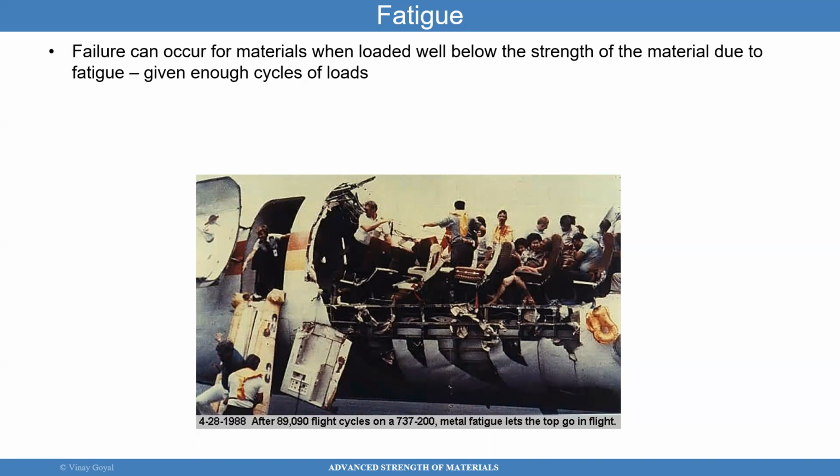And when you take off, the pressure inside the cabin is pressurized to typically 5,000 to 7,000 feet, and that is done to keep the passengers comfortable. But the air outside drops in pressure as you ascend, and that causes a delta pressure across the fuselage.